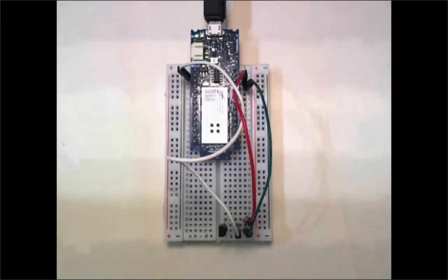And I've multiplied by a number which I've left as a division. So instead of putting a constant 0 point something something, I just set the number to give you an idea of what I'm doing. So I'm dividing 3,300, which is essentially 3.3 volts in millivolts, by 1,024 steps, which tells me how many millivolts per each number I read from the Arduino.